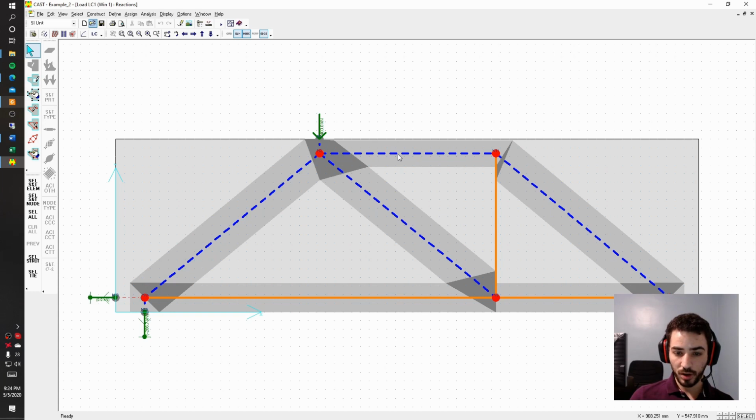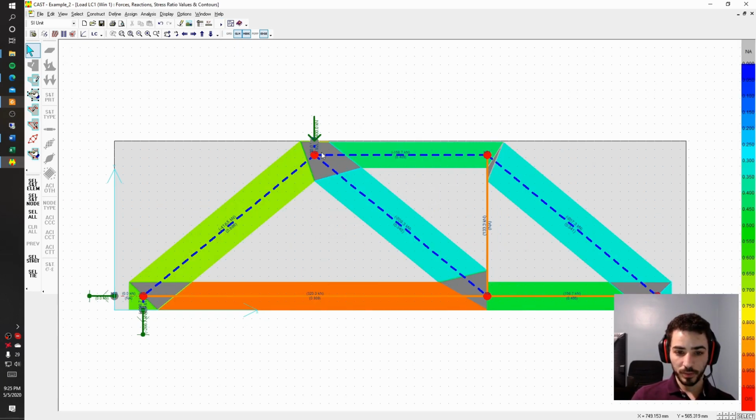And this strut is the same as the tie, bounded by the thickness that it has to the edge of the element. So this is to illustrate how we can use strut-and-tie to design our stirrups or our vertical reinforcement in an element. So if we run this system, we should have the results of each element, and everything should pass in this case.